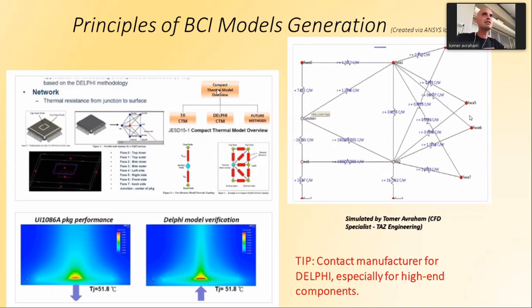It necessitates that you open the JEDEC and see what boundary conditions there are. So if you have a client or a system engineer who wants a thermal analysis at 55 ambient, you cannot tell him, no, I'm doing it at 15 degrees, because that's when it's valid.